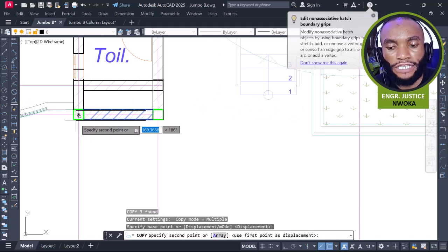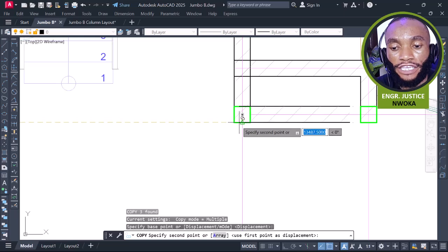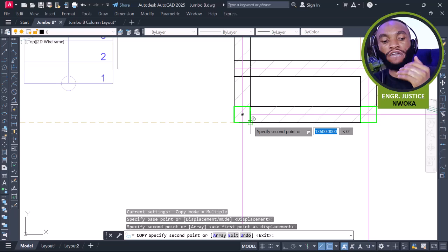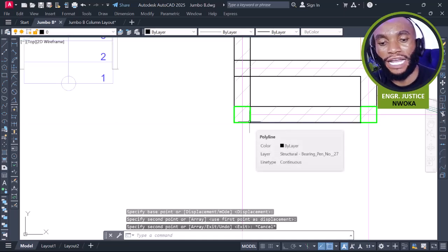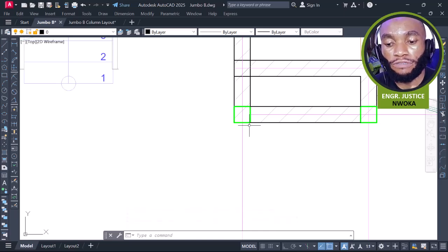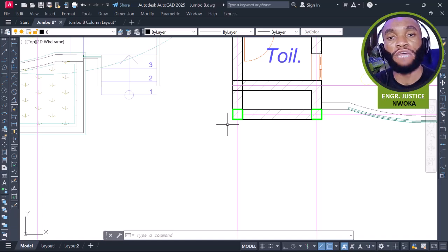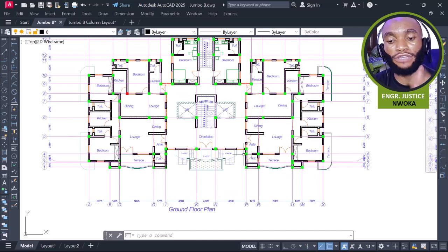GA basically tends to be very, very boring, but that is the time a building will collapse, because now you are going to frame the structure and perform its connectivity between members. If you don't spend time on this level, then you have issues in your design. So always spend time when you're performing your design, your framing of your structure, else you have issues in that design. Okay, that's fine.